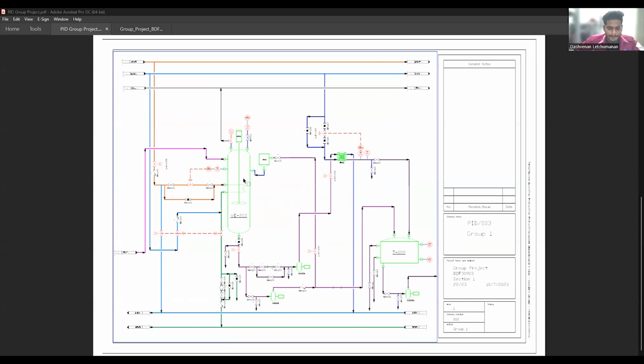So the product from the VE203, after heating at the certain set point, will be transferred by the pump. We have two identical bypass pumps, of which P203A is operated mainly, and if it is in maintenance, the P203B will operate. So it will pump the CPO into the heat exchanger, while the heat exchanger line will pump the cooling water